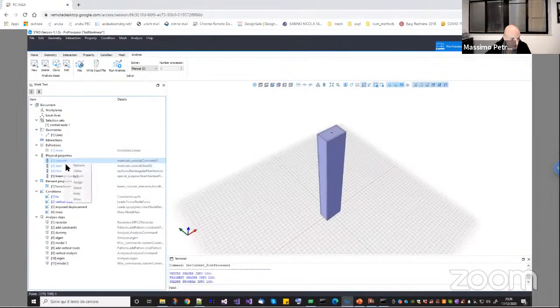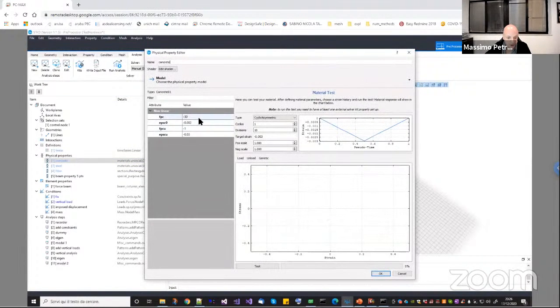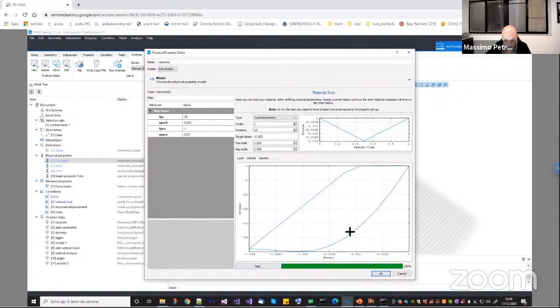And my material model for concrete has a peak stress of 13. So if I run my test now here, 18 is about here. So as you can see, it's a very small nonlinearity, okay? The problem is, what happens if your tangent stiffness is about here? It will be 0. So you cannot compute the eigenvalues around here.